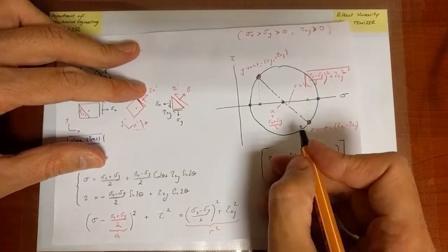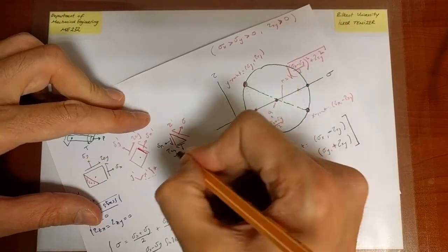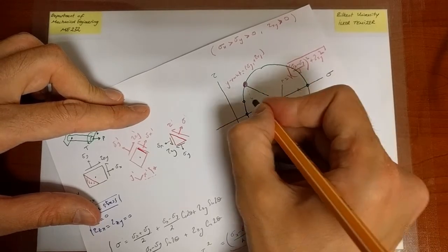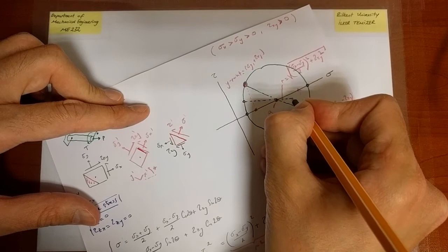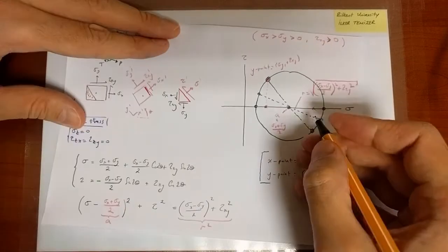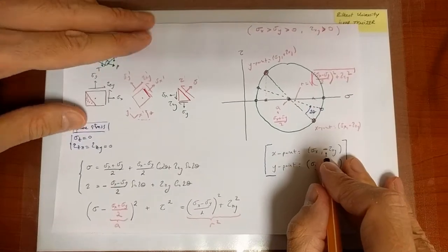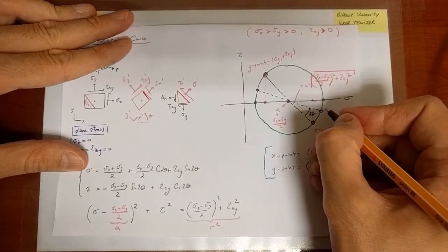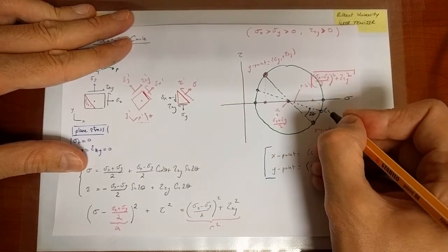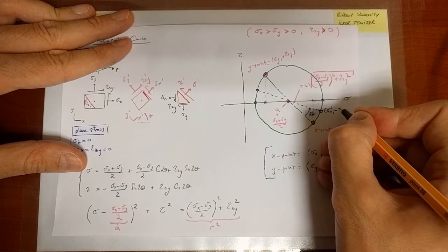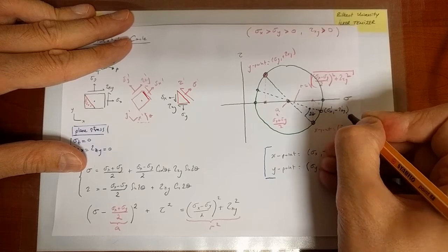So in other words, if I rotate through an angle theta on this picture, I am going to eventually move through an angle 2 theta, to a point where now I have a new normal stress value, sigma x prime, a new shear stress value minus tau xy prime.